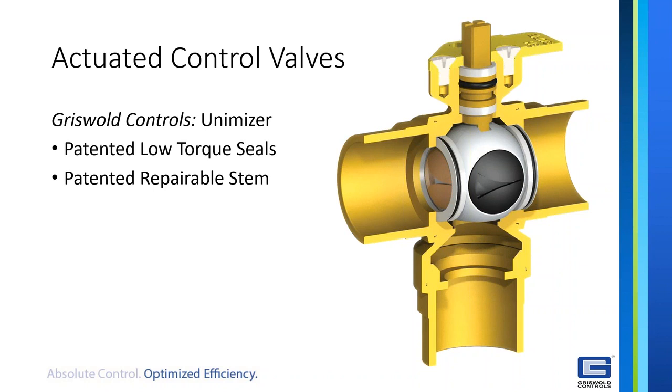It's even more amplified when you go into the larger 1.5 inch all the way up to 3 inch valves. For Griswold, we're still up to 3 inch at a 35 inch-pound actuator, and every other competitor on the market is at either 80 or 88 for maybe the 1.5 inch, but then definitely 2 inch, everyone's at 120 to 140 inch-pound actuators.